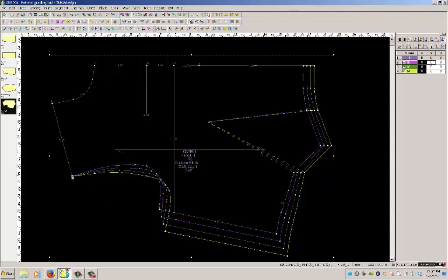It's going to increase in the X direction, meaning that it is actually going to my left. So X actually increases as a -1/16. So it's going to my left. It's -1/16. Y is increasing by 1/8 of an inch. Increasing means it's going down, so I type in 1/8 of an inch.